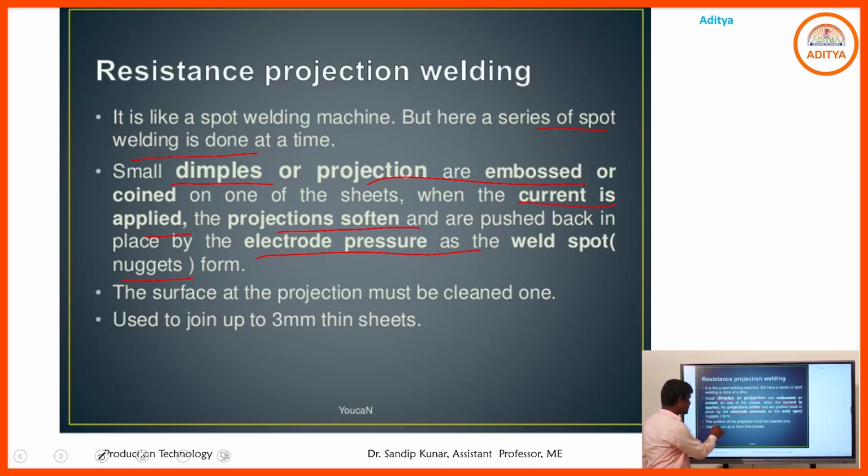The surface at the projections must be cleaned before welding, meaning all the spots or projections must be cleaned properly, otherwise the weld quality will deteriorate. Up to 3 mm thin sheets can be joined using that resistance projection welding process.